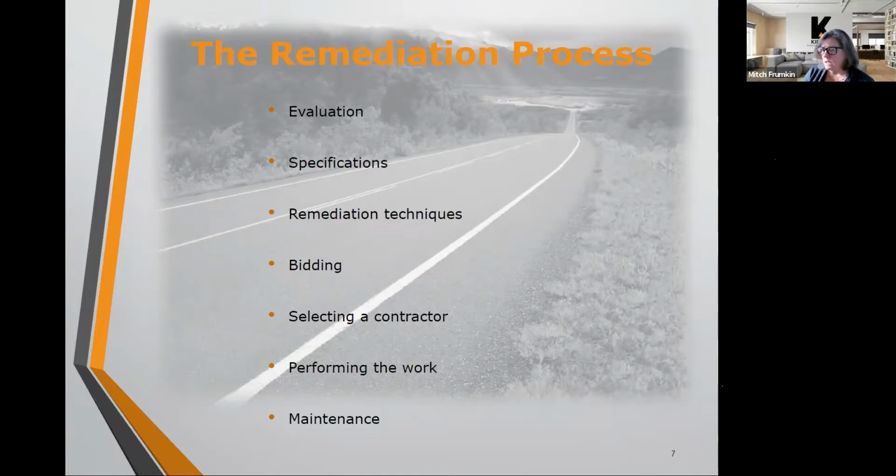But that contingency amount of between 10 and 20% will typically capture things such as base repairs and changes in asphalt price and concrete work that may need to be done where the pavement meets sidewalks. It captures a number of things that are unforeseen, but we find it's typically around 15%.